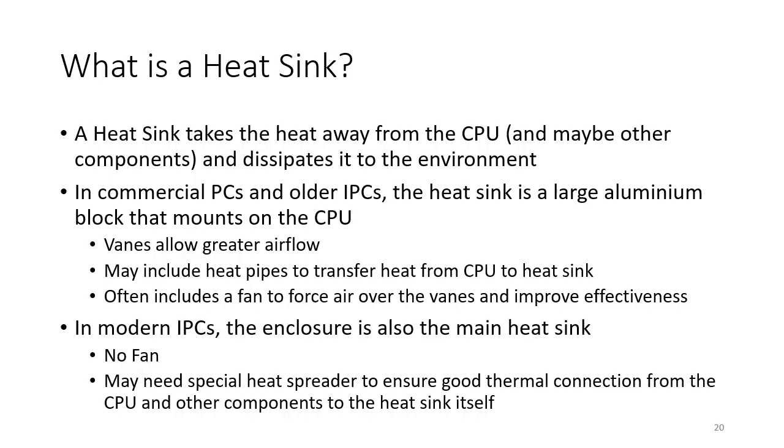So sometimes that might mean if you're putting an industrial PC inside some sort of cabinet, you may need to install fans in the cabinet itself in order to get that correct airflow. And it also might mean that you need to make sure that you've got specific airflow as well in terms of vents in the enclosure to allow for airflow. Again, there's quite a bit behind heat dissipation inside the cabinet that I'm not going to go into, but if you really get into it, that may need some sort of consideration.